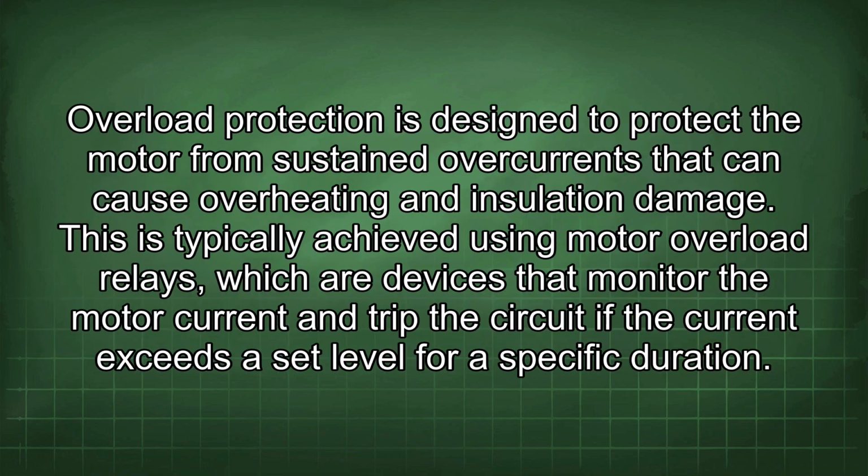Overload protection is designed to protect the motor from sustained overcurrents that can cause overheating and insulation damage. This is typically achieved using motor overload relays, which are devices that monitor the motor current and trip the circuit if the current exceeds a set level for a specific duration.